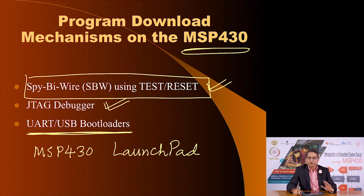it is able to download code into the memory of the target microcontroller, and not only program it, but you could debug your program by single stepping through the code, which means execute one line of program, stop there to see what is the result of that program by inspecting the registers or variables, and then going to the next instruction, and so on and so forth.